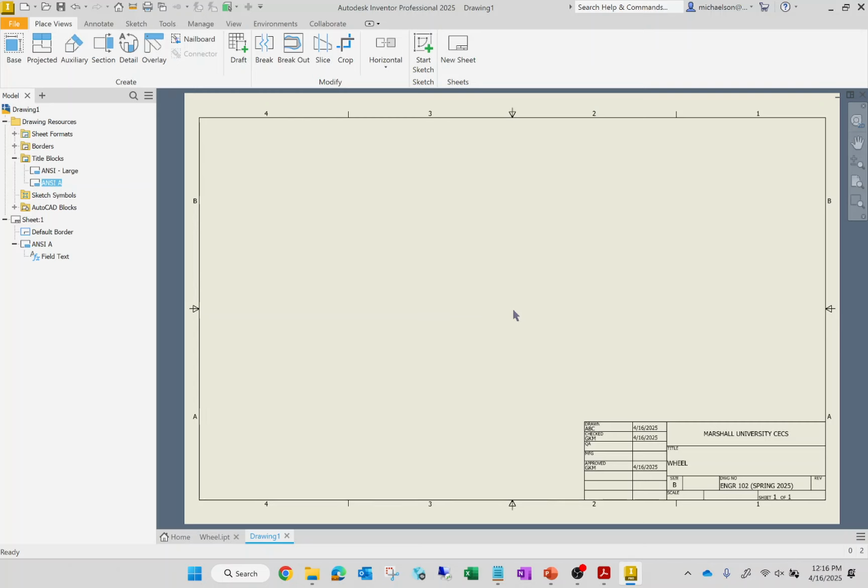So you're going to hit cancel, and then you're going to go in and edit the sketch. So you can go in and edit this sketch. Oh, the sketch looks good. Now let's go back to the revolution. So the axis needs to be, click that, needs to be that line. No problem. Okay. All right. Everybody good?